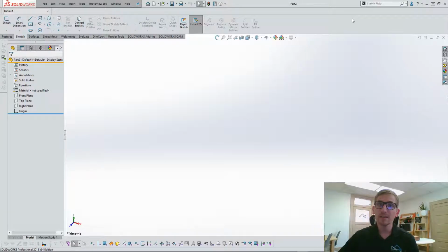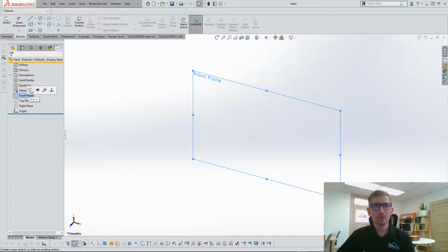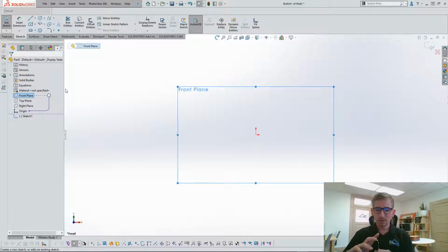Okay, so as I was stating, I would come in and create a sketch that would give you your reference of how big the item should be, and then import your picture on that. So let's say, for instance, on this pen, I come on here and I'll do a new sketch on my front plane. Well, this pen is just a long cylindrical item, and it's just vertical in this instance, right? How I'm looking at it. So I'm going to simply draw in a line, because when I measure this, I measure from here to here. So that's just, as the crow flies, a straight line.